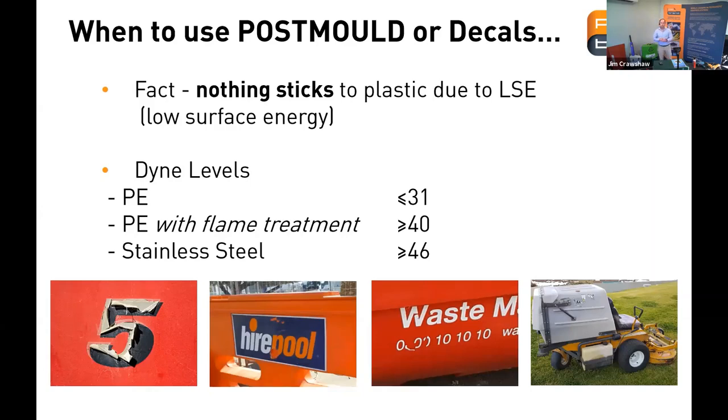So when to use post-mold or decals? Well, good question. The fact is nothing sticks to plastic due to the LSE or low surface energy. Just out of interest, many of you probably already know this, but polyethylene has a dyne level of less than 31 dyne, compared to stainless steel, where you've got 46. So you might notice that decals stick really well to stainless steel, but not so well to plastic. That is a very real reason.